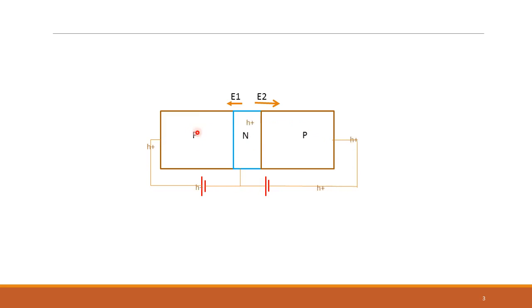So the hole current, the minority carrier here, which was being injected from the p-type, instead of going out through this terminal, goes across this reverse biased PN junction and then goes around like this. This actually constitutes a current in this direction.